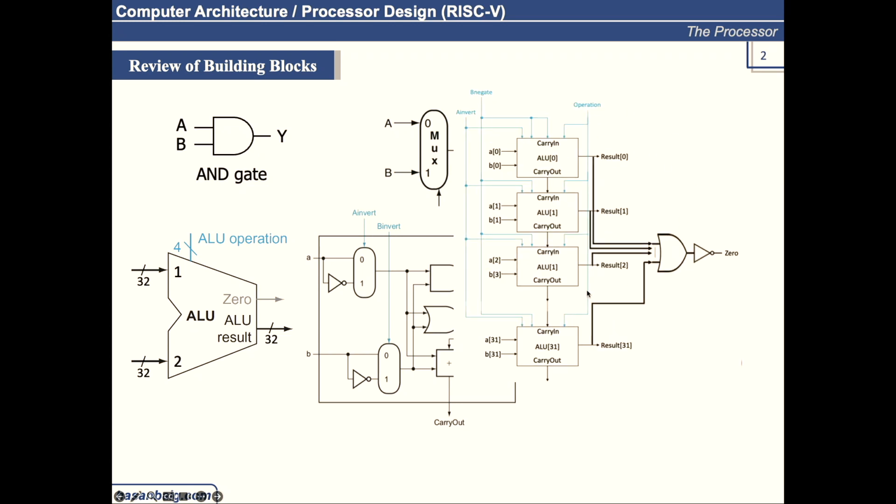And to perform the branch instruction, what do we do? In the branch instruction, let's say BEQ. What is the format of the branch instruction? BEQ X1, X2, and then the label. So what do we do actually in this branch equal instruction? We compare the contents of 2 registers. If they are equal, then take the branch. And how do we compare?